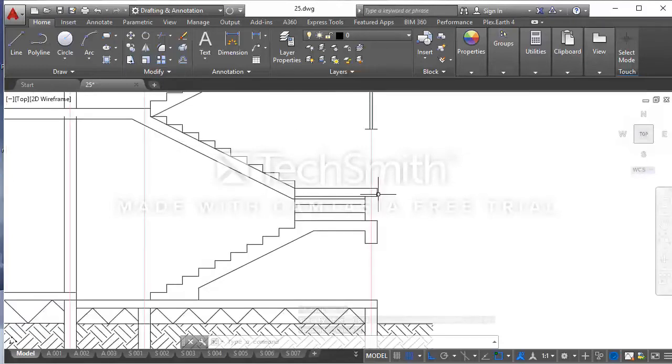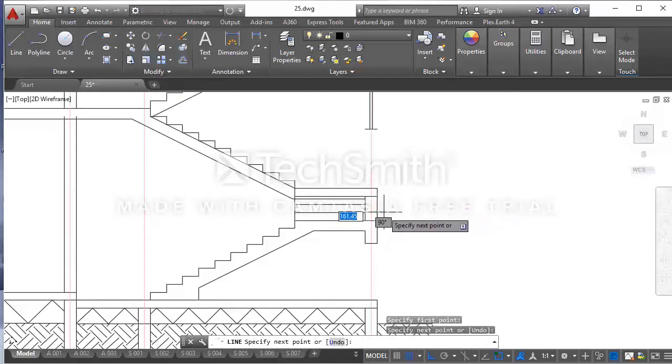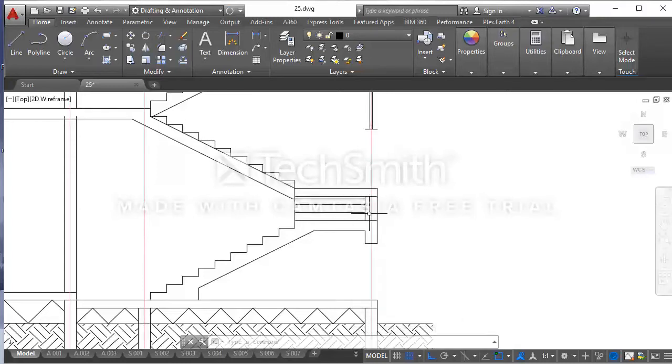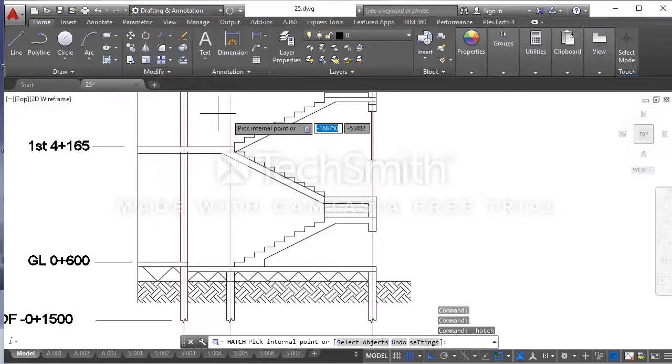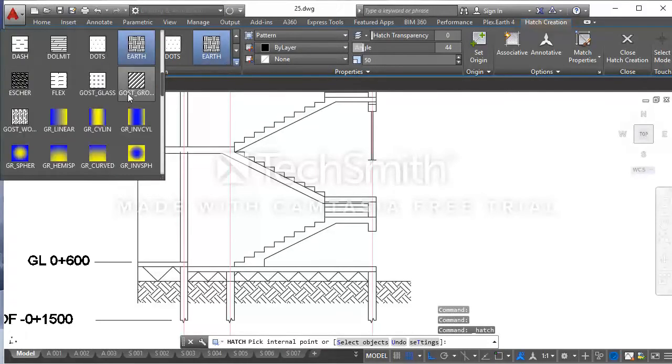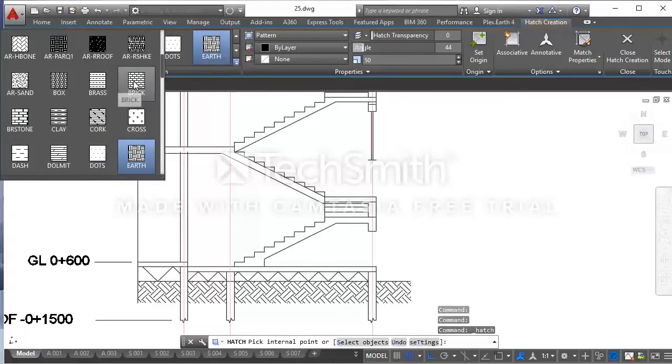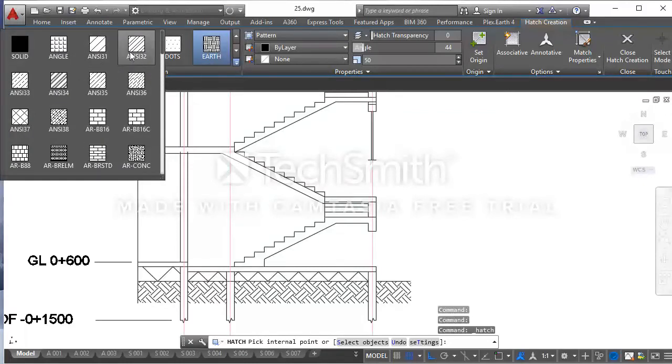So yeah, I told you that I'm not providing a beam here. Instead, I'm going to place a wall here to support the third flight. So I'm going to apply a wall hash pattern there to denote the wall. Very important to denote it so anybody looking at the drawing will know how the beam is supported.